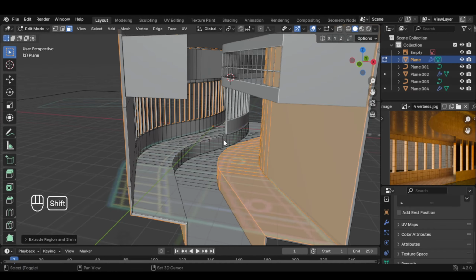What we can do is add these pillars now, so we can see them here, these round circles. So we're gonna press Shift and right click, so we can move the 3D cursor here. Press Shift A and add a cylinder. Go to edit mode and press S and Shift and Z, so you can make it thinner to about here.